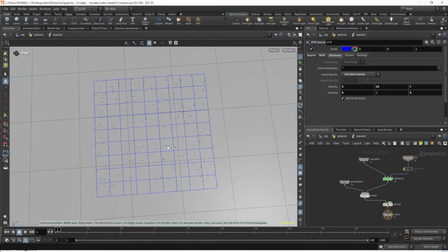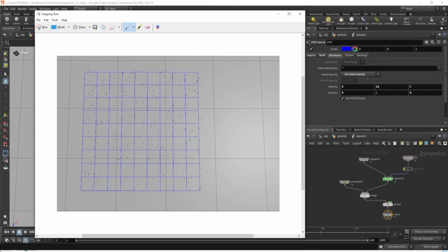Cool, let's talk about collision. So here let's understand, do particles collide with each other? So no, they're too tiny, so they don't collide. But if you want to add particle collision, then you have to set p scale. P scale we will talk about when we render this. But for now, let's just understand. So you can just set a p scale, basically the radius of the particles. And after that, you can run a grain solver, so they will collide with each other. And also, if you want to add collision, it will increase simulation time 5 times or 10 times.